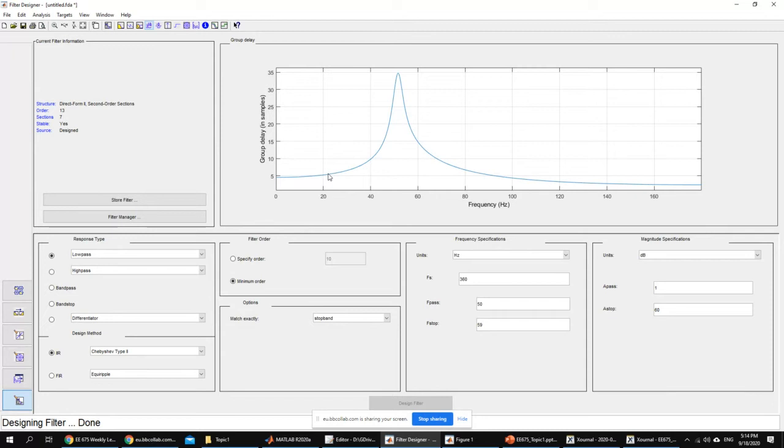So what you should do is use the IIR filter and try to see whether the output has some additional artifacts that weren't there before. But you should just be careful about this group delay issue. In any IIR type of filter, you're going to have a group delay that looks like this.